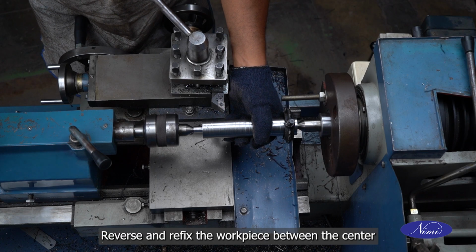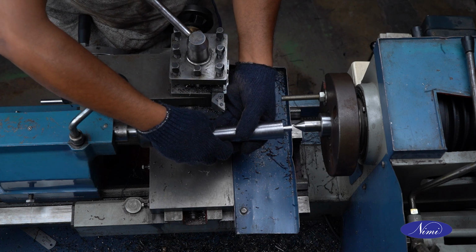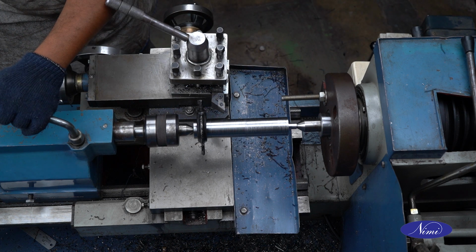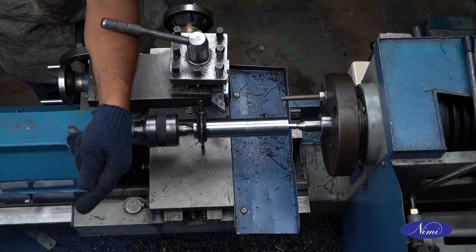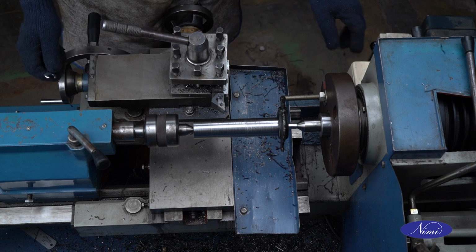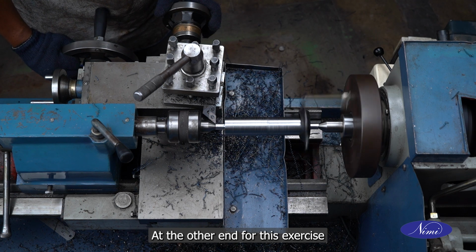Reverse and refix the workpiece between the centers. Step turning operation for 15 mm to obtain a diameter of 12 mm at the other end.